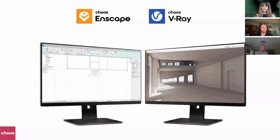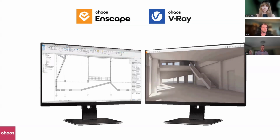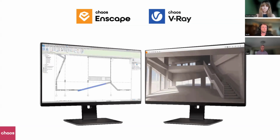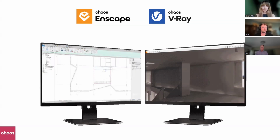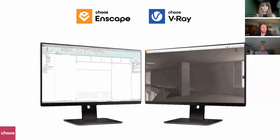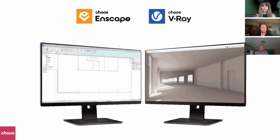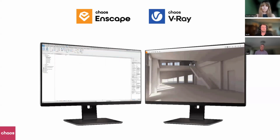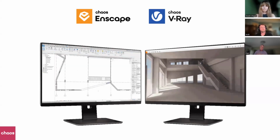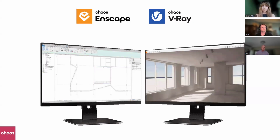As a plugin, we can only view and render what's inside the BIM model. You can't aggregate models or compose scenes from models coming in from different softwares. For example, you can't aggregate in V-Ray or in Enscape a landscape model coming in from SketchUp with a building model coming in from Revit and some architectural ornamentation maybe coming in from 3ds Max or Rhino. V-Ray and Enscape are purpose-built to view only the data that's in that host application.